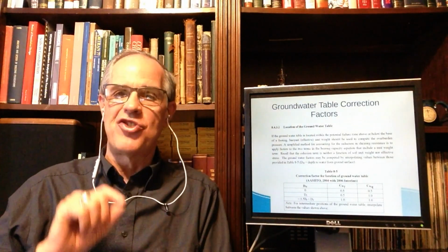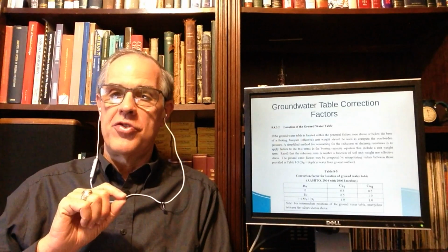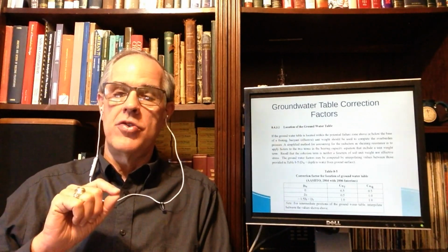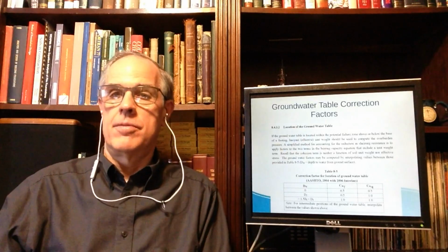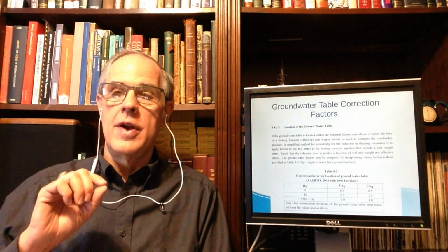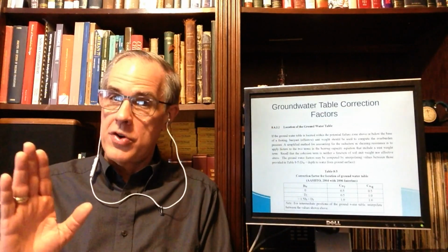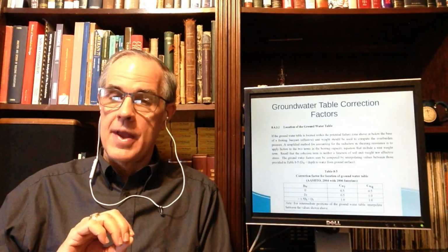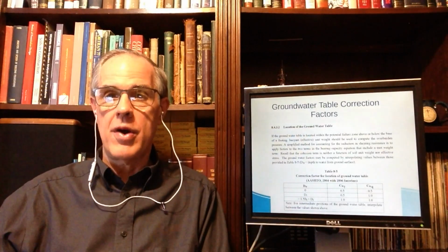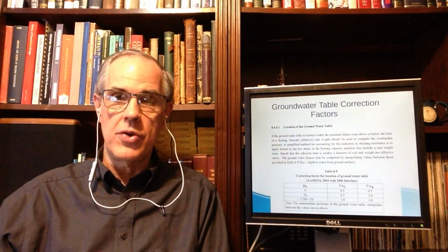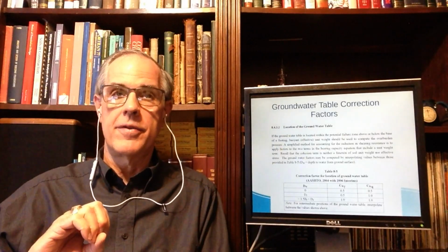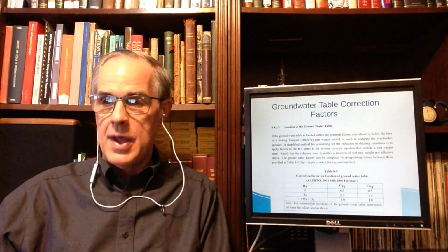And the weight of that soil mass bears upon the failure surface. And if that failure surface is cohesionless, you remember that the strength of any cohesionless soil is developed by weight applied to the soil particles, which in turn induces friction. If you have groundwater interfering, the strength is, in general terms, proportional to the effective stress. If you flood it, saturated all the way to the top, you reduce that effective stress, and you reduce basically the ability of the foundation to resist shear. And that's basically what you're dealing with.